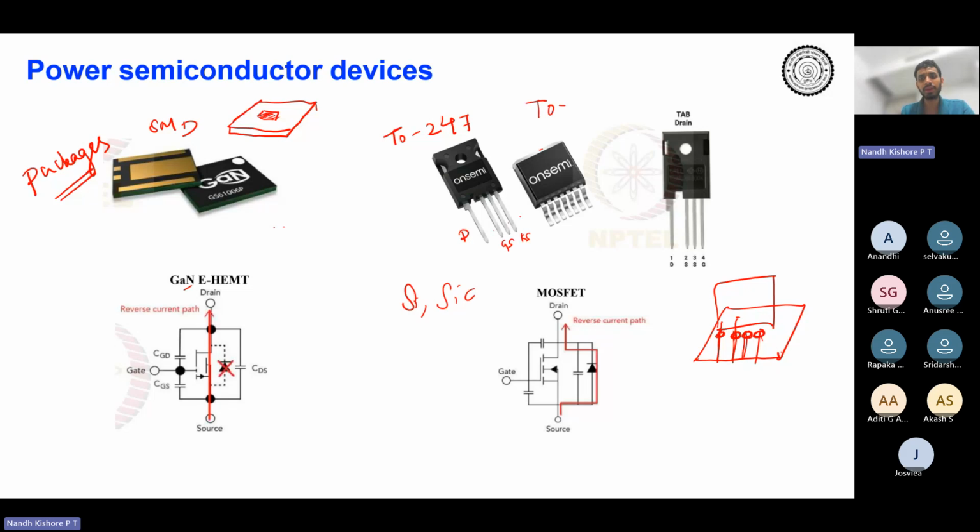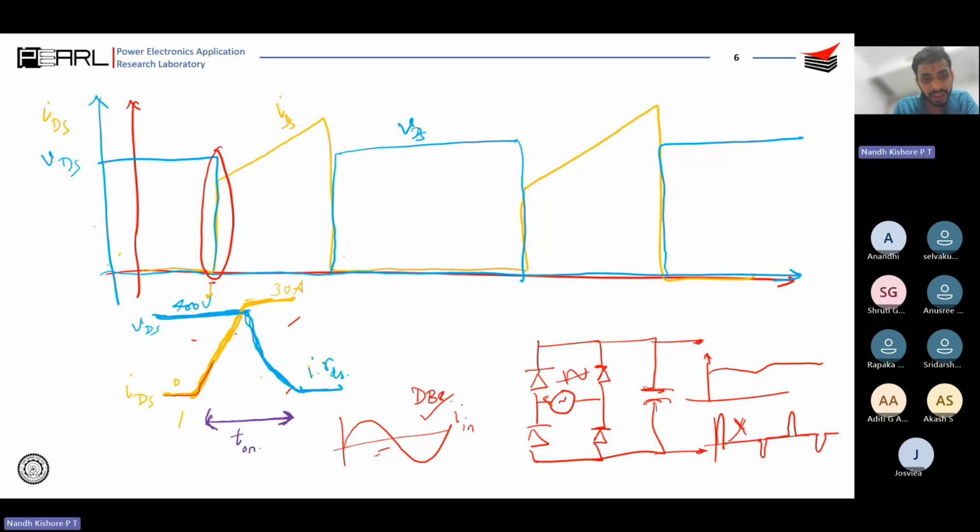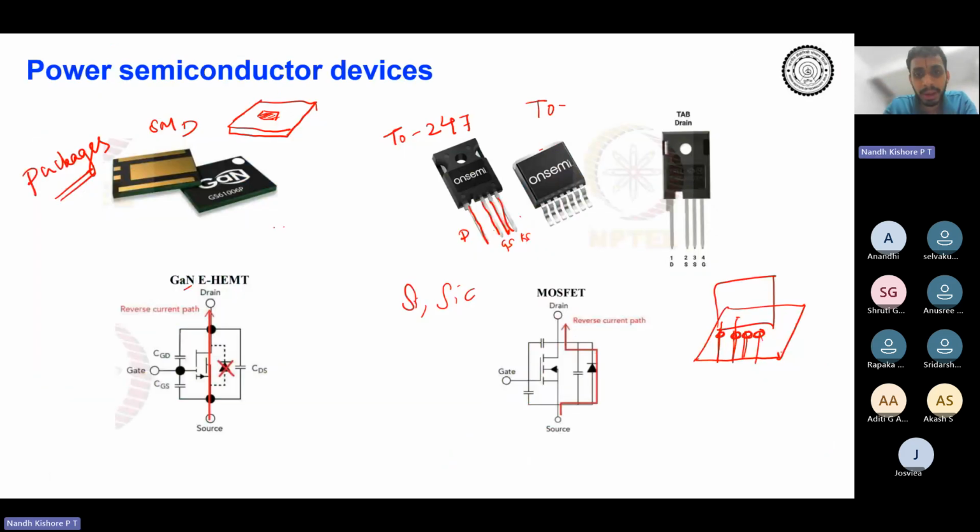And you might wonder why these are important, but you will understand that these leads over here are very crucial for device switching. As I was mentioning over here, you might see something like this, or even something like this. This overshoot and this time are all functions of small parameters like these leads. These leads can make a huge difference in terms of the turn on and turn off times.